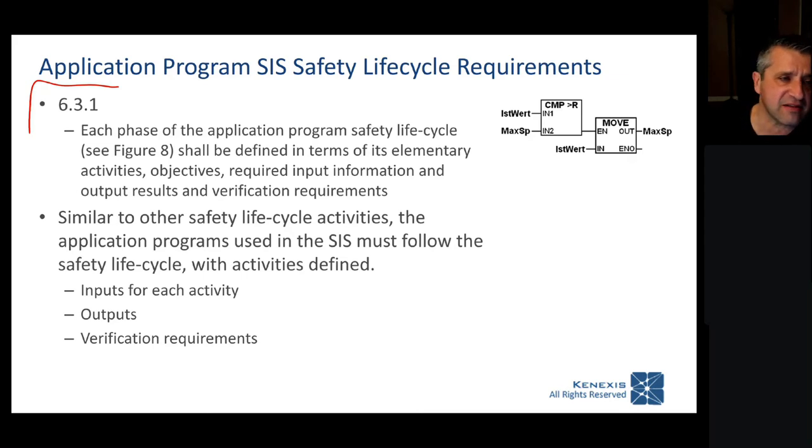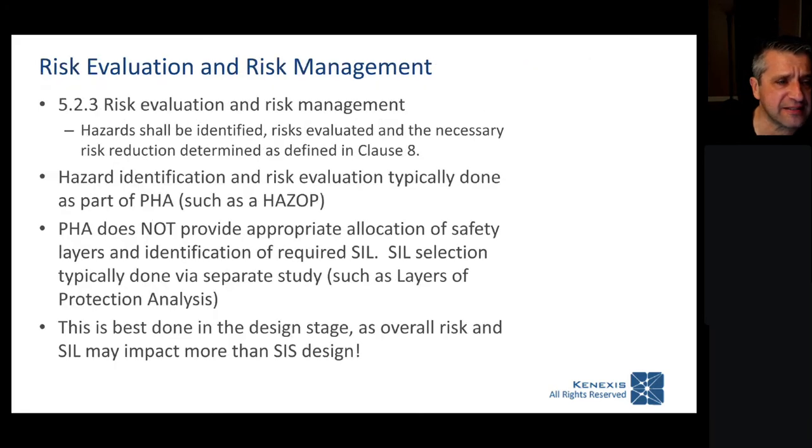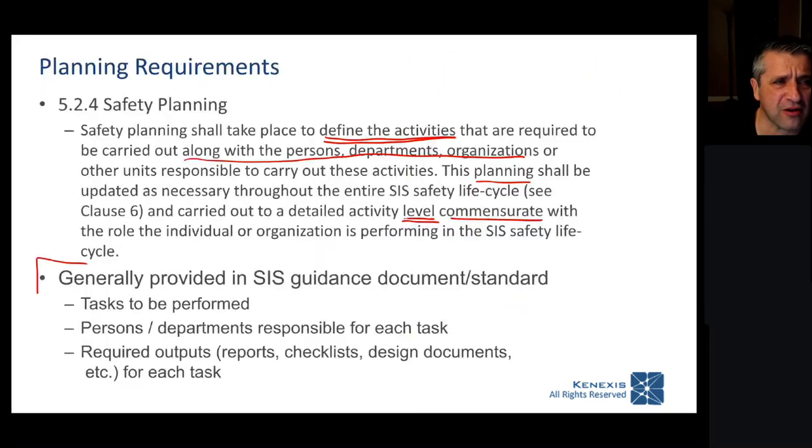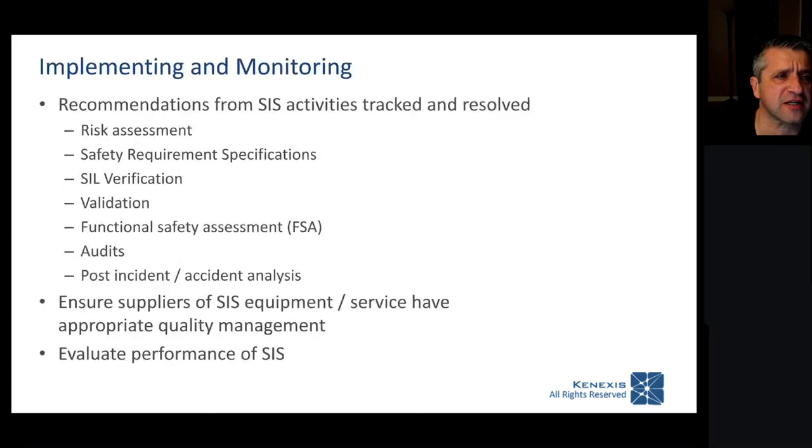But the key to this slide and the key to statement 6.3.1 is that software is part of your SIS design, and you need to document it and manage it exactly the same way that you're documenting and managing your hardware design. Okay, so that is a little bit of clause 5 and some of clause 6.